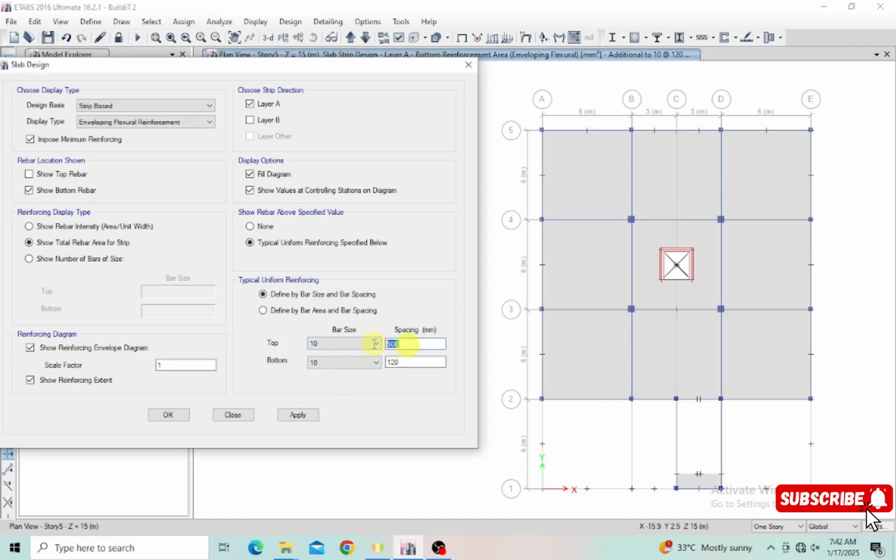Wow, still it's going to be okay. So with the 10 mm bars at this spacing, it's going to be okay for layer A. Let me check for layer B too. They are all going to be the same. So most of the higher bars, higher things are going to be at the top.